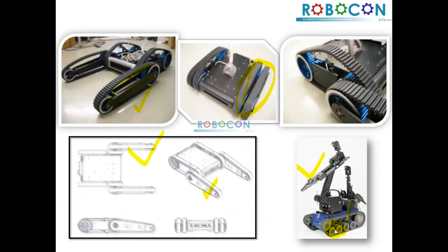You can have another look at a wheeled robot system, where a protruding arm of the wheeled robot is being shown over here. This arm can again rotate and fall back in line with the robot chassis. This kind of robot is very useful in robots used for bomb disposal squads, or robots which can climb stairs very easily, because you can change inclination very easily with these front cantilever arms.